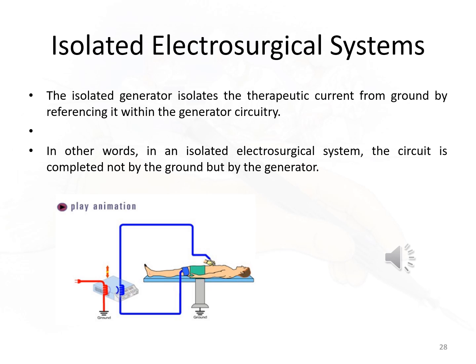Electrosurgical current from isolated generators will not recognize grounded objects as pathways to complete the circuit. Isolated electrosurgical energy recognizes the patient return electrode as a preferred pathway back to the generator. By removing ground as a reference for the current, the isolated generator eliminates many of the hazards inherent in grounded systems, most importantly, current division and alternate site burns.